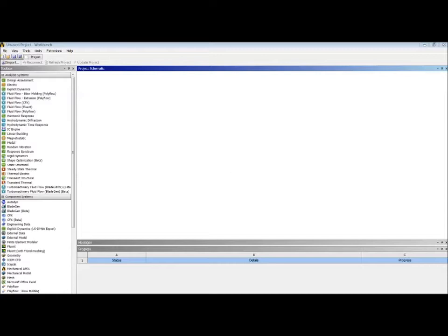Okay, right, so let's start with the ANSYS Workbench. Bring up your ANSYS Workbench, and the first thing we're going to do is double click on FLUENT. This starts our FLUENT analysis. Just so we are clear, we are going to start with the laminar boundary layer simulation of AF106, and we're going to use U equals 1 meter per second there. Then double click on the geometry.